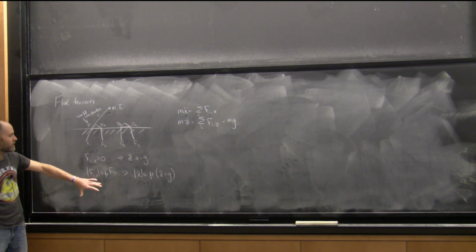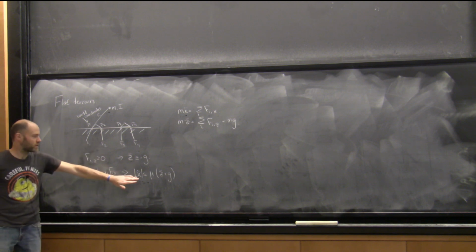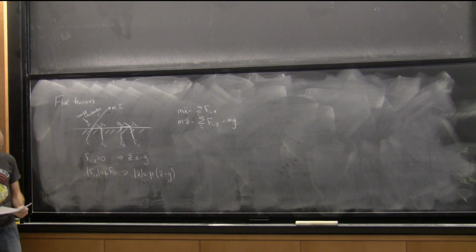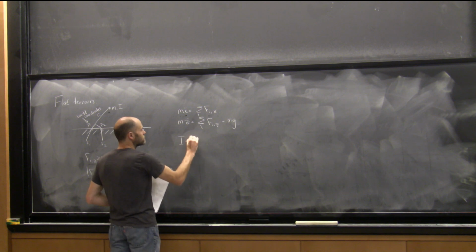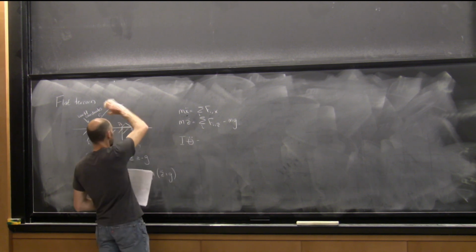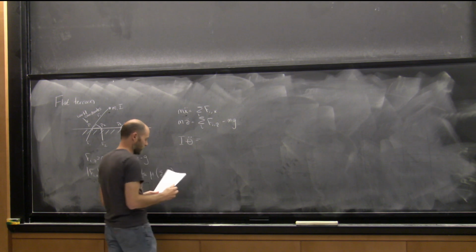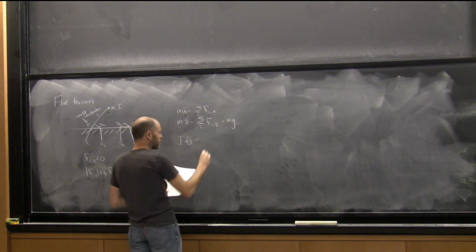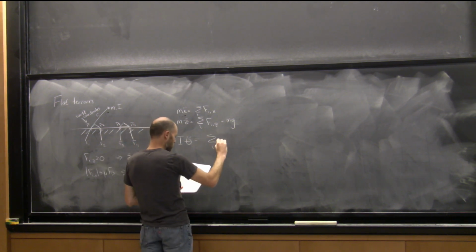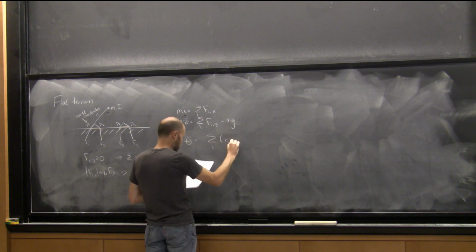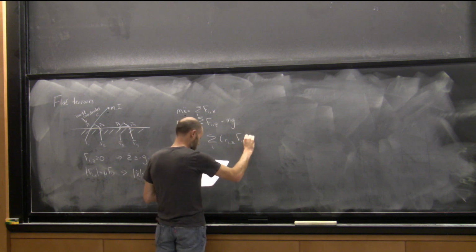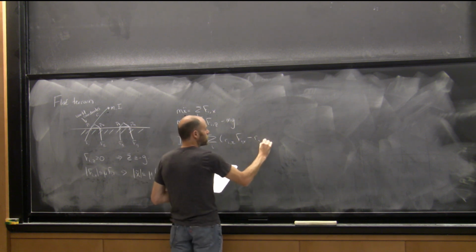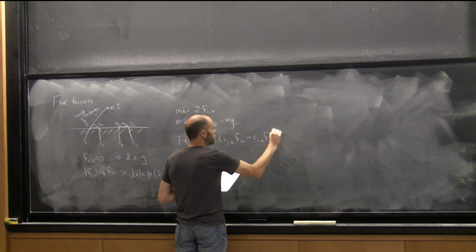Cool. All right. So force constraints confer constraints on my center of mass. It turns out it's actually even more than that. If I look at my angular momentum constraints, just thinking about the rotation around this as if it was a single rigid body, is the easiest way to derive it. It's Ri Z Fi x minus Ri x Fi Z.